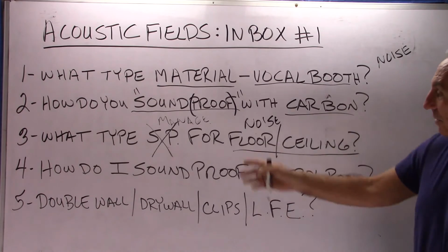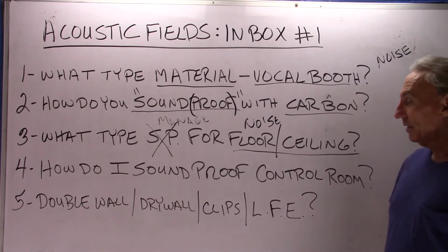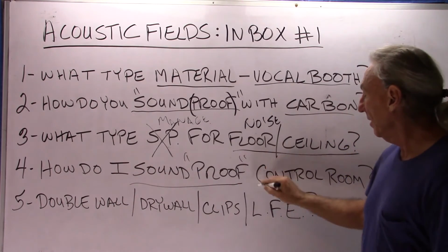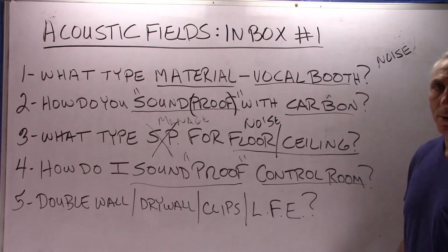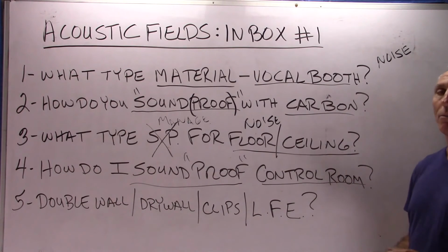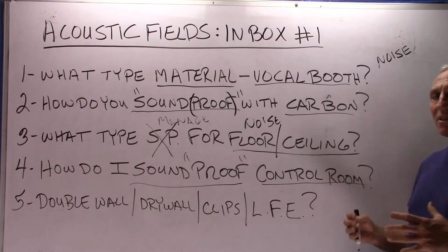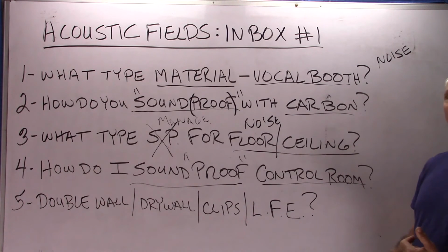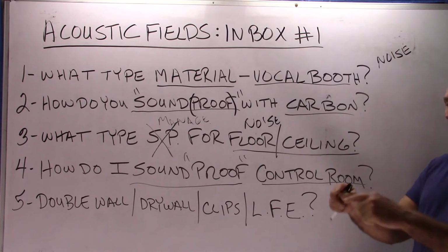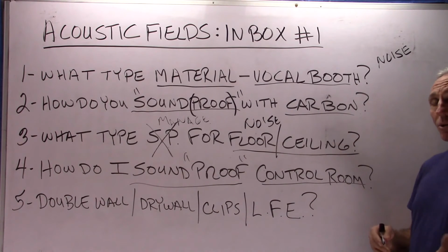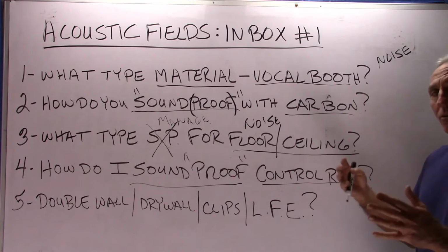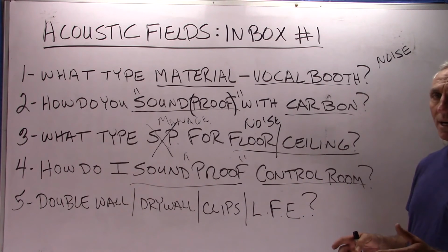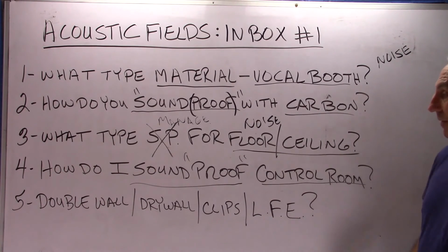Okay? So how do I soundproof a control room? Well, same issue here. Soundproofing, no such thing. And for a control room, we have to know a lot of other things. That's why I came up with that room form that you fill out, because that at least gets it started. That gives us size and volume and usage. And then we have the number of energy sources in the room. So if we know the size, we know the volume, and we know what you're trying to do in the room, then we can treat accordingly for the barrier or the treatment side of the room inside, all usage dependent.